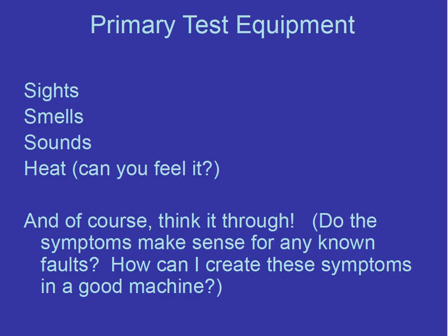In case of printed circuit boards, you can look for any overlapped traces, and you can also observe the soldered points, whether they are correctly soldered or not. Check for any shorts or touches on the adjacent soldered joints. So these are some of the things you can look for when you are troubleshooting the circuit.